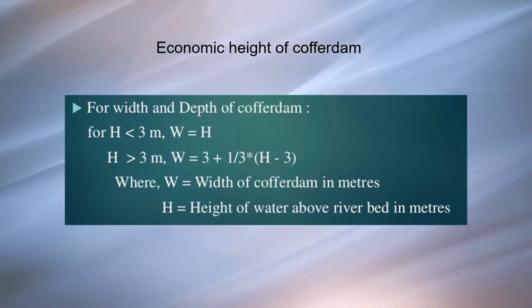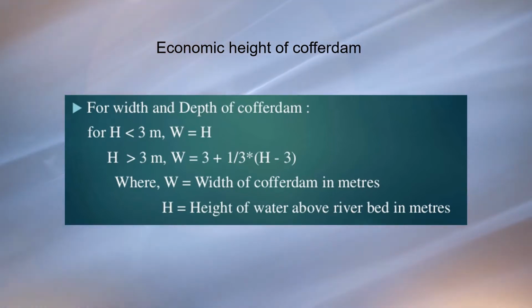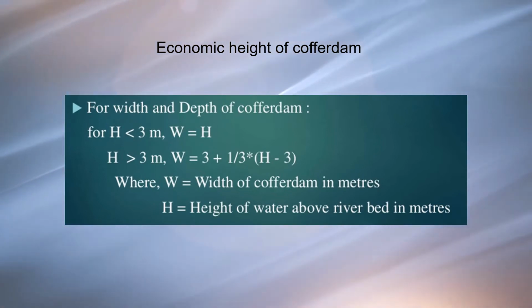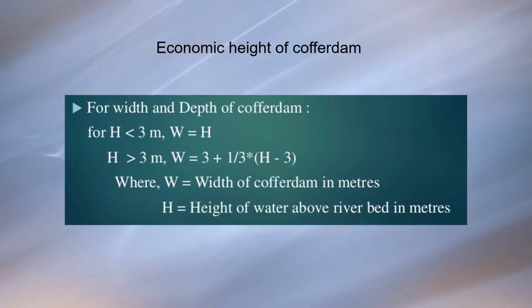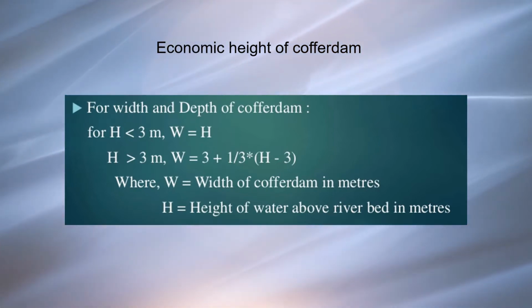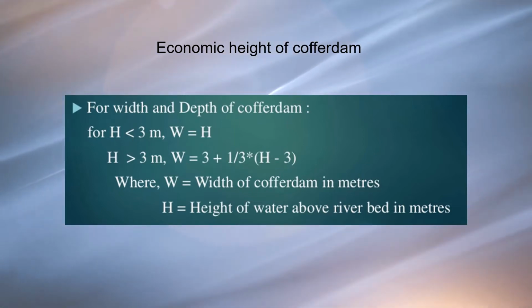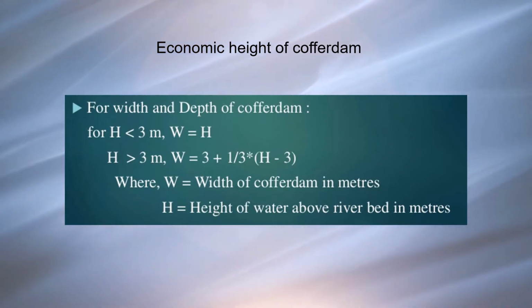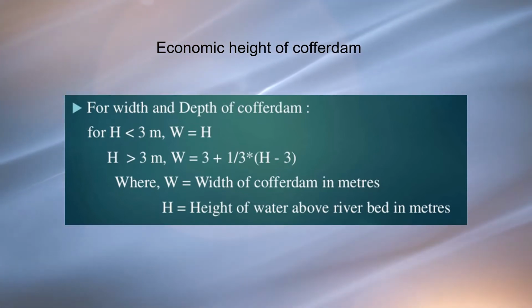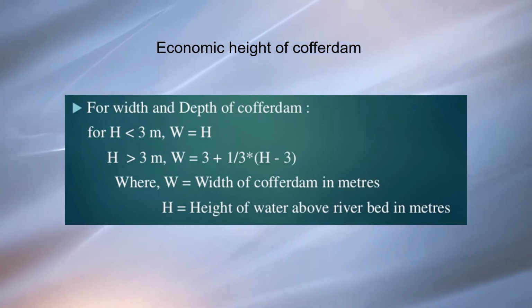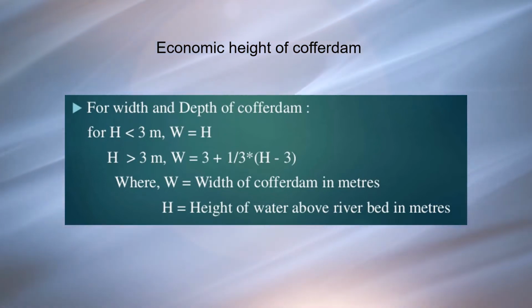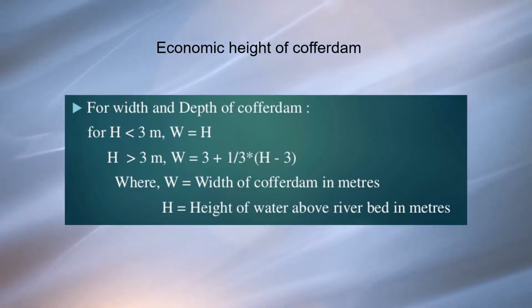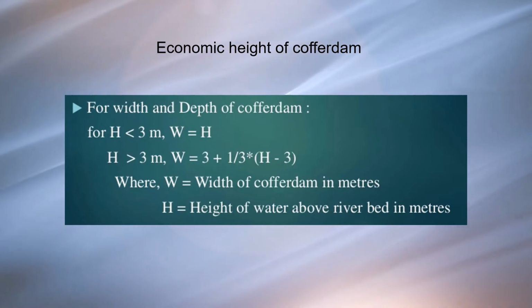Number 3. Type and period of work. For short duration of work, timber cofferdam can be used. Meanwhile, for long duration of work, sheet pile cofferdams can be used. Number 4. High and low tide level. Sheet piles must have top level slightly higher than that of the high tide level, so that even in the extreme case, water cannot overtop the cofferdam, to achieve the dry working area.